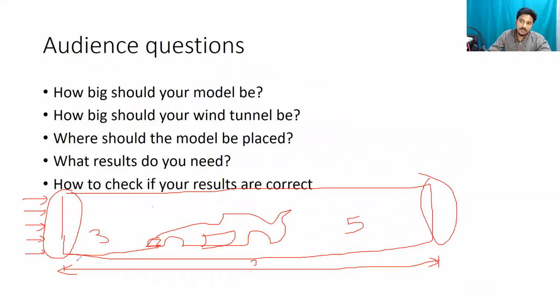So one of the things that people want you to validate is that your boundary layer development should match what is reported in the experiments. So if experimental data is available, you just make sure that you follow that for the inflow length, meaning the upstream length. As far as your outflow is concerned, it's not 5, it's at least 10 times the length.